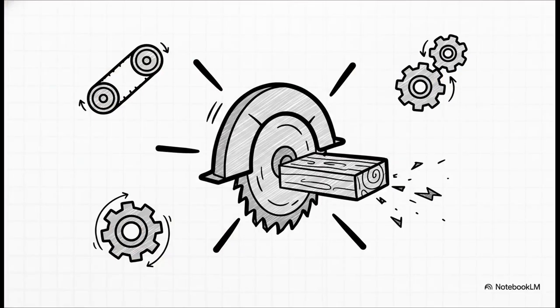Let's walk through the big 5 mechanical hazard zones on our floor. The absolute most crucial one is number 1, the point of operation. You must be hyper-vigilant here. That is exactly where the tool physically engages the work, where the cutting, shaping, or boring actually happens. Consequently, it's where the vast majority of our injuries occur. Following that, we have power transmission apparatuses, nip points, rotating parts, which by the way is any spinning mechanism like a spindle or shaft that can tangle you up, and finally, flying chips, sparks, or loose parts.